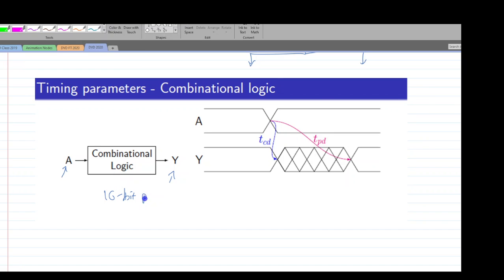Okay, and when we had a 16-bit parallel adder, we know that when there is a propagation of carry, S0 would be produced, then S1, the sum at bit position 1, would be evaluated first, and then later S2 would be evaluated, and in that way, all the way our S16 output would be produced. Okay, so what is happening is that I'm not getting immediately the sum output of all the 16 bits at a single time, whenever there is a propagation of carry through this carry chain. Clear?